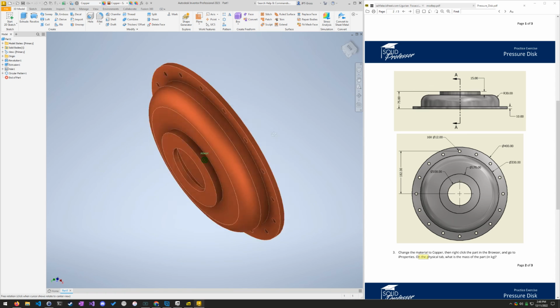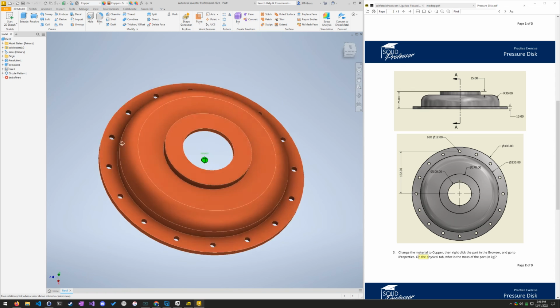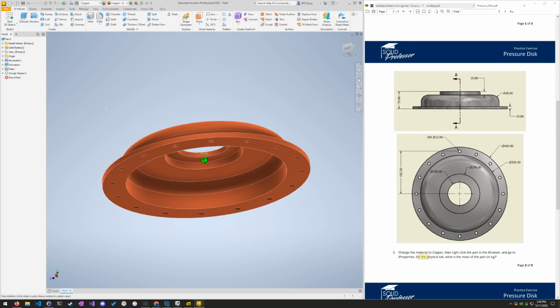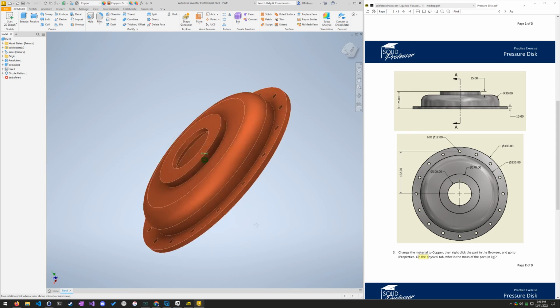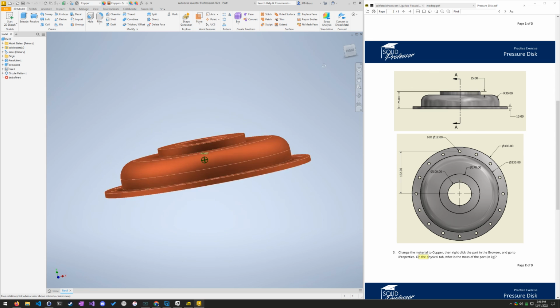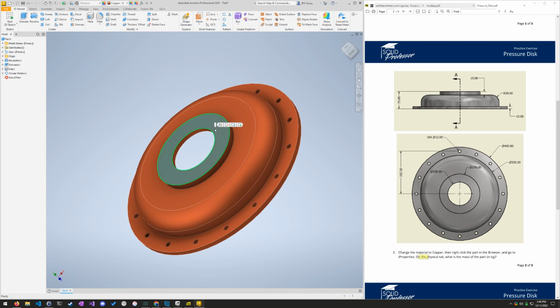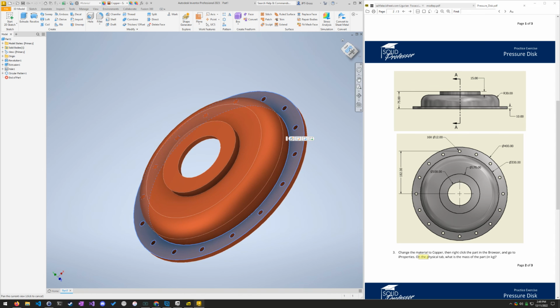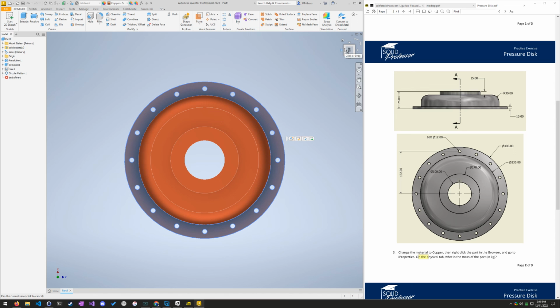I hope this helped you to make this shape and learn a little bit more about the way the revolve tool works. It's incredibly useful, especially for something like this, because without it you would have to create a lot of circles and then extrude down, create another circle, extrude down, fillet this rounded edge, create another plane, another circle on another plane, and extrude down. It's so much easier. You do one sketch, revolve it around, done, and then we put in the holes.